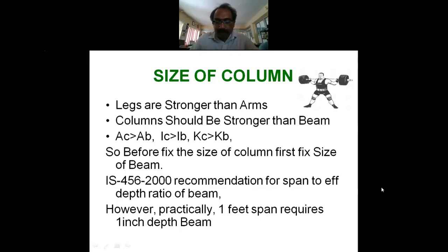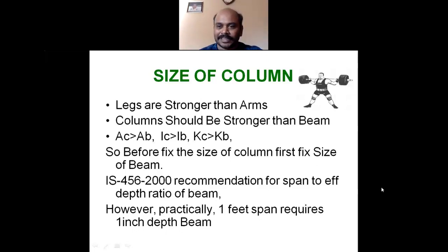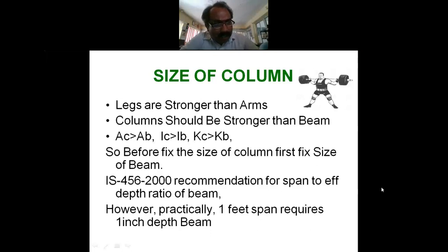What is the range of soil or lateral soil found in South India, particularly in Kerala? Kerala is mostly laterite soil. Some places, like around Cochin, also have marine clay. But as a civil engineer, you should approach the way a doctor approaches every patient. All over the world, people have A, B, O, positive, negative, AB negative, AB positive blood groups, and some rare Bombay blood group. But these are information known to everyone. So don't generalize. Again and again I am insisting, if you are going to do a project at a particular site, you have to test the soil at that particular site.